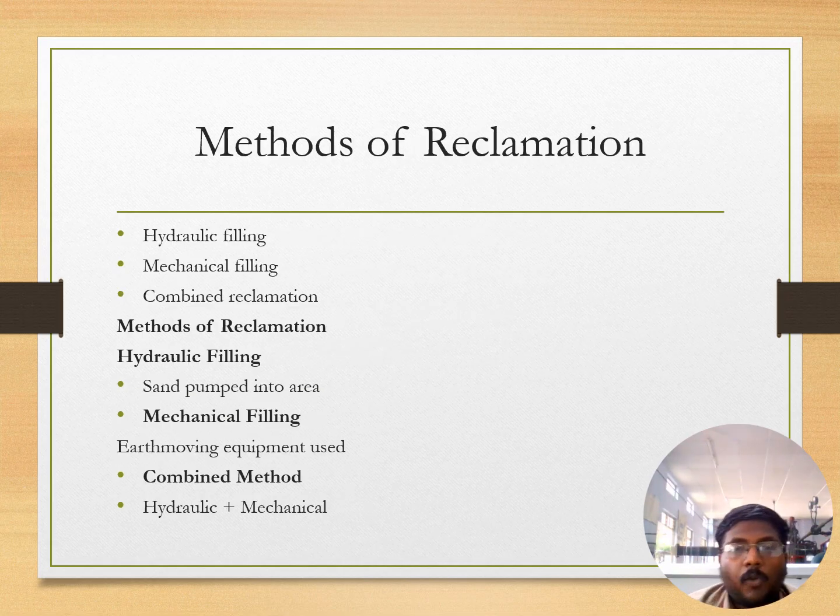Next we see about the methods of reclamation. There are three different methods that should be followed: hydraulic filling, mechanical filling and combined reclamation. In hydraulic filling, sand is pumped into the area. In mechanical filling, earth moving equipment should be used. In combined reclamation, both hydraulic filling and mechanical filling should be used for the development of the entire area.